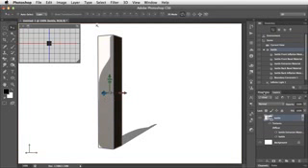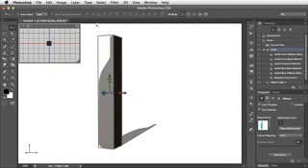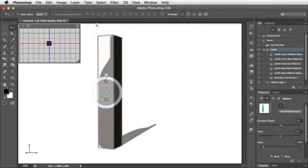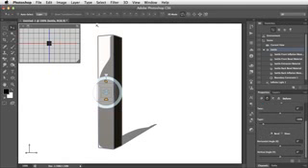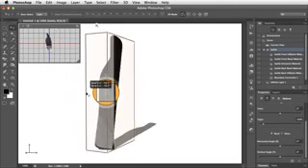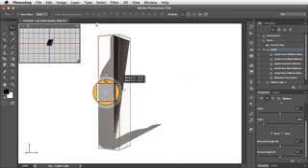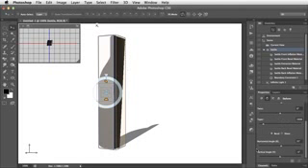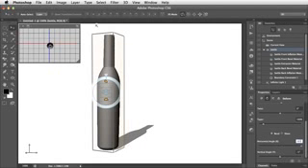If we select it, we can go to the Properties panel, and now in the Deform section, we can say we want to bend it. And we've tried bending it before by dragging on the little bend head-up display here, and we can see how we can create these interesting shapes out of it. If we use the numerical entry instead, we can create exactly the shapes we want. So let's rotate this at a horizontal angle of 360 degrees to make a complete circle, and set the vertical axis to 0. And there is our basic bottle shape.